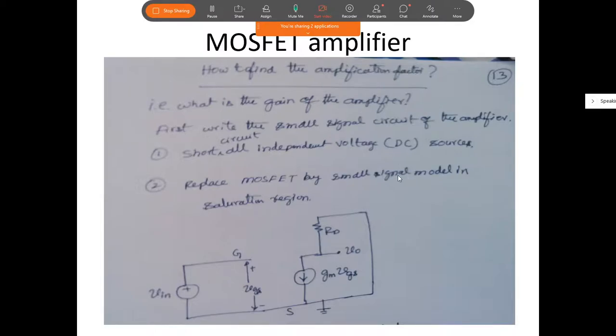What do you mean by this? Sir, to get only AC sources. Why do you want to short the DC? So for constant amplitude. No, it is not so. Even though the DC is higher in amplitude, since there is no variation in it for the AC signal, even though the DC voltage is 1.8 volt or 5 volt or 3 volts, it looks like a short circuit.